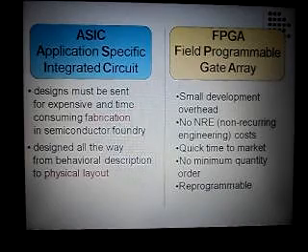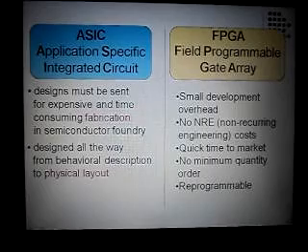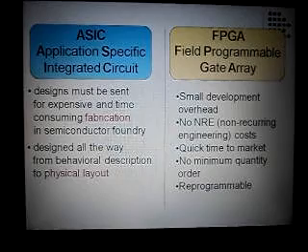And among other advantages of FPGA, the manufacturing cycle for ASIC is very costly, whereas for FPGA it is not very lengthy and engages less manpower, whereas ASIC requires a huge amount of manpower. In ASIC development, mistakes normally detected at the end of the design level are not correctable, whereas in FPGA you can correct any problem at any stage of development.